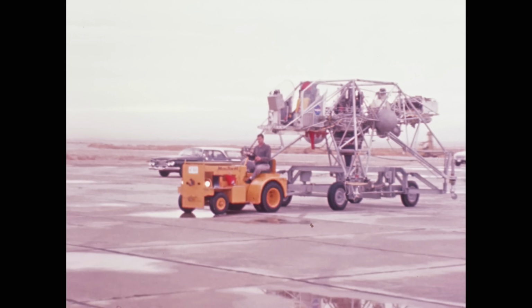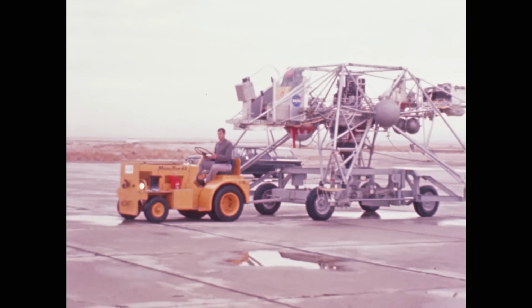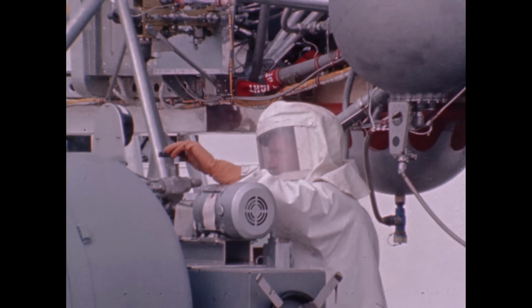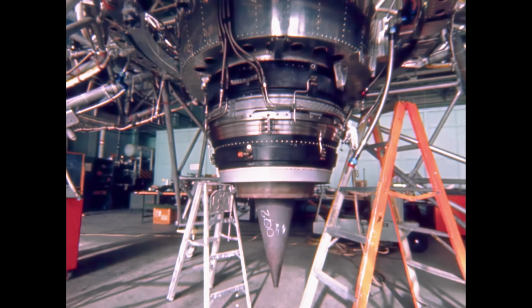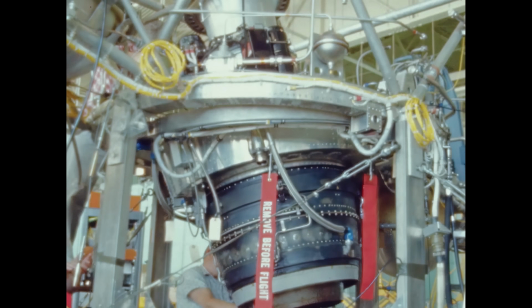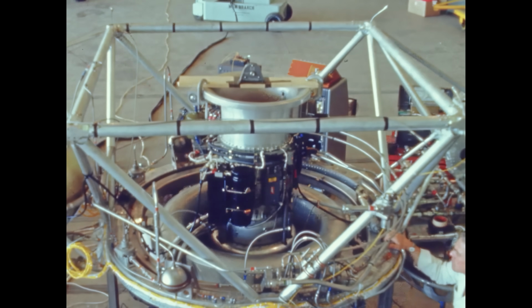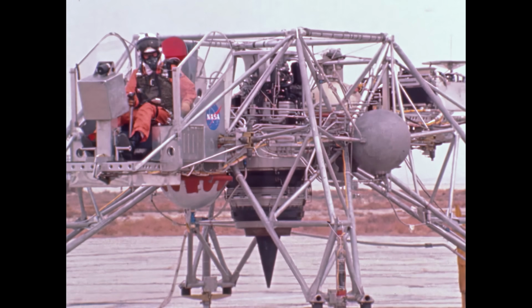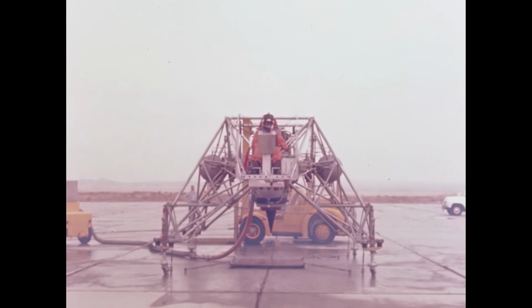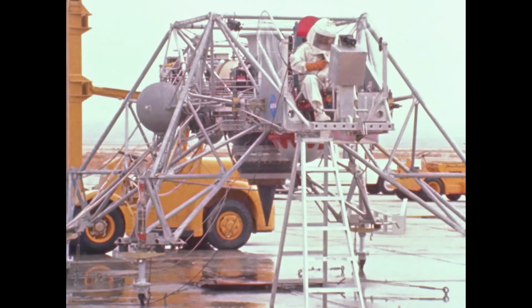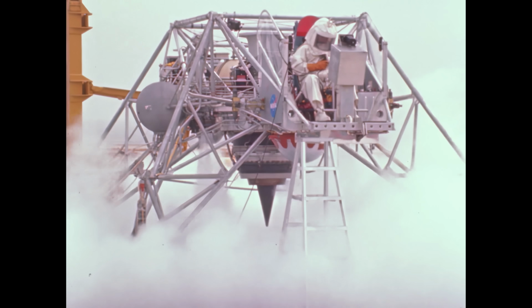The proposed technique for simulating the lunar gravity was simple in principle. Reduce the apparent weight of the craft to its value while flying over the moon. The proposed method: install a jet engine underneath or within the machine on gimbals, so the thrust was always vertically upward. The engine thrust would then be adjusted so that the craft's net weight, that is its gross weight minus the engine thrust, would equal its lunar equivalent. The force required to lift the net weight would be provided by throttleable rockets.